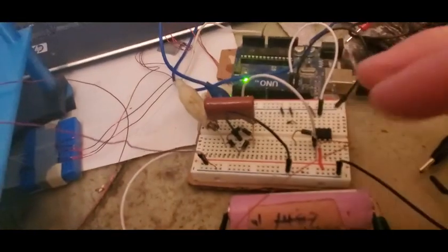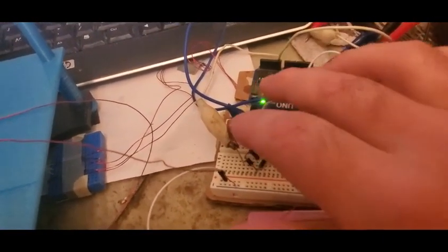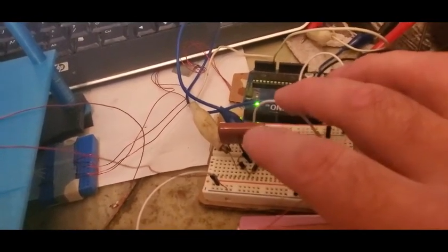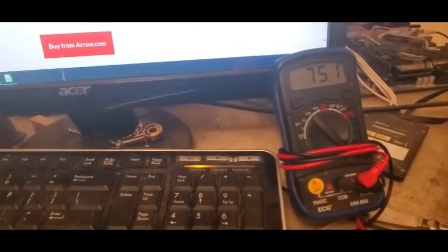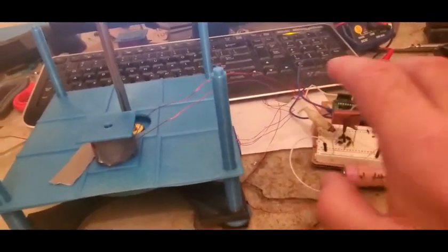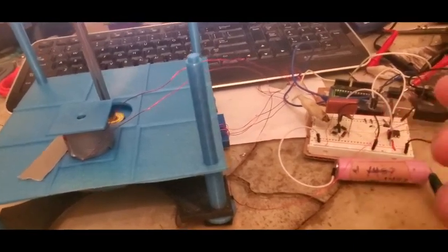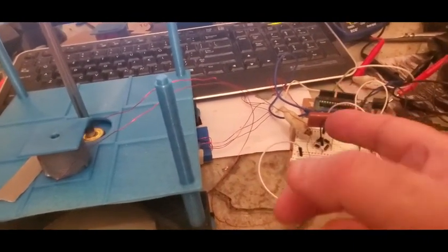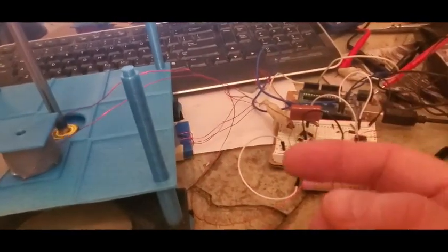Okay, so now we have the inductive spike being rectified by a full wave bridge rectifier. These two lines should both be orange or something. This is just what I had lying around. But the positive and the negative are where the cap is. The spike is 75 volts, 75.1 versus it was 76 before. Rotational speed's about the same. I'm not going to bore you with the 1K and the 10K through here. What it boils down to is that it's pretty much the exact same. It's just a little bit worse with the full wave bridge rectifier because you're going through 2 diodes instead of 1.